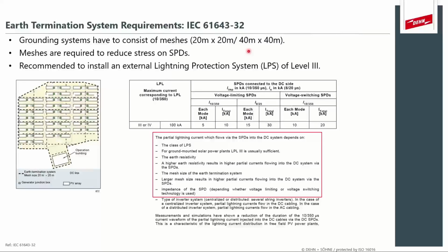Now, this value is extremely important for how the lightning protection system will operate. It's something that we managed to change and adapt quite a bit by using simulation software to not strictly adhere to a 40 meter by 40 meter mesh, but to form some form of meshing that's mixed between above ground and underground material. Now, this value is extremely important for what you will see throughout the rest of the presentation.